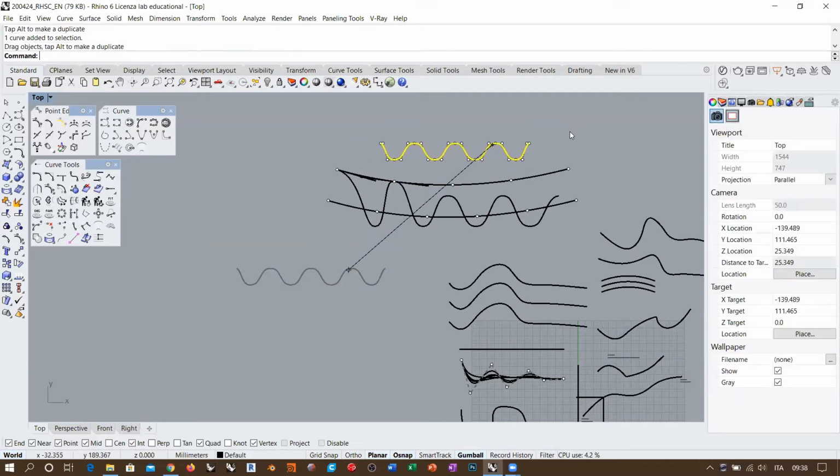So when you need, for example, a global adjustment of the topology, because you are going to create some kind of extensive deformation along the lines that you are using, then in that case, you might want to use the rebuild command. So this is something that you do in order to simplify the topology, but increasing its complexity, right? Because you are taking into account that if you increase the amount of control points, you are still working with a uniform rebuild. So their distribution along the path is going to be extremely regular, okay?